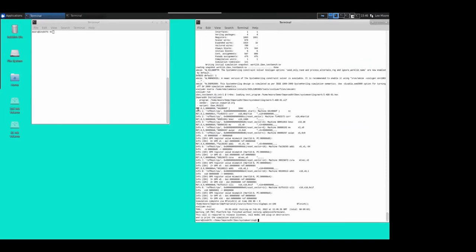It tells us that an instruction was retired on hart 0. Its order was 1, so it's the first instruction, and it tells us the address of that instruction, the bit pattern of that instruction, and the disassembly of that instruction. It also tells us that there were no register updates associated with that instruction, which is what we would expect, because there is no change at that point.